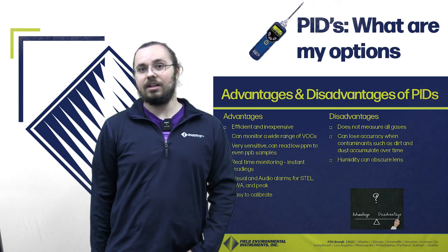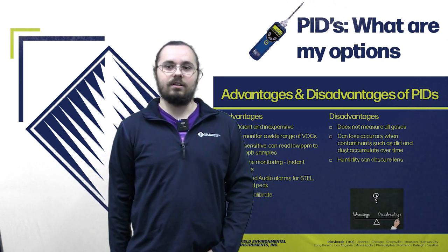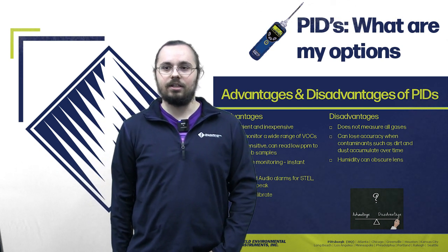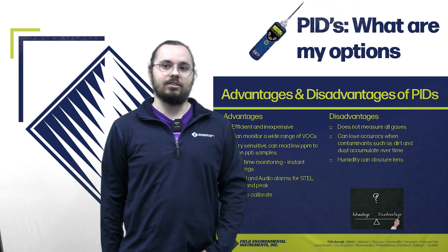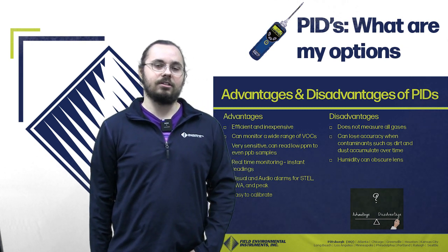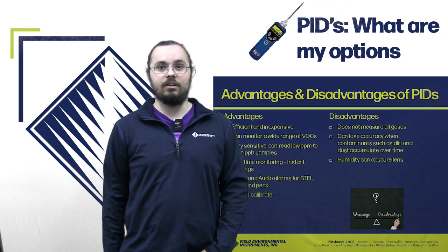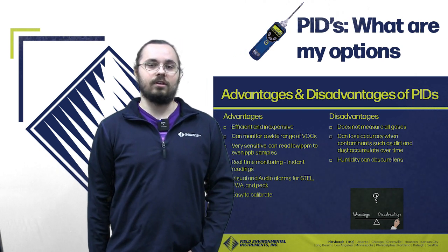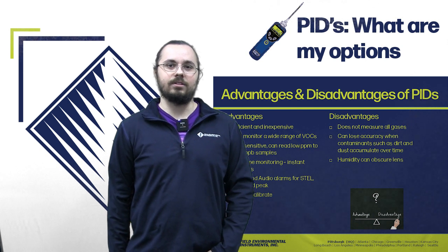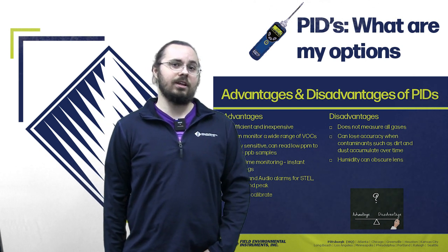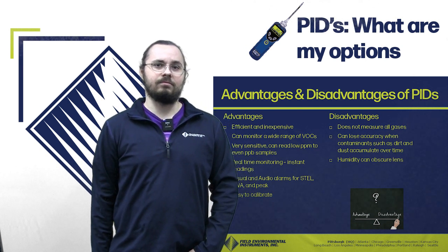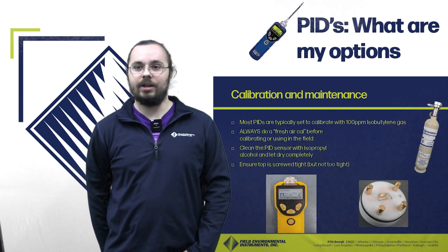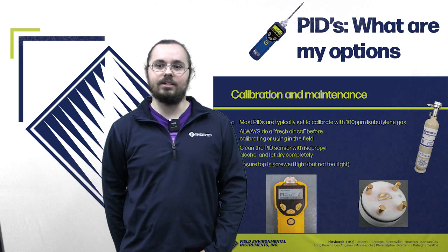Some disadvantages that come along with them is, of course, they cannot measure all gases. There's a lot of things they can't detect. And they can also lose accuracy as contaminants such as dust and dirt accumulate on the PID sensor and lamp. Humidity is also another big factor that can affect their performance, but there is a way to combat that, which we'll talk about a little later. Next, let's go over some basic tips on calibrating and maintaining your PIDs.